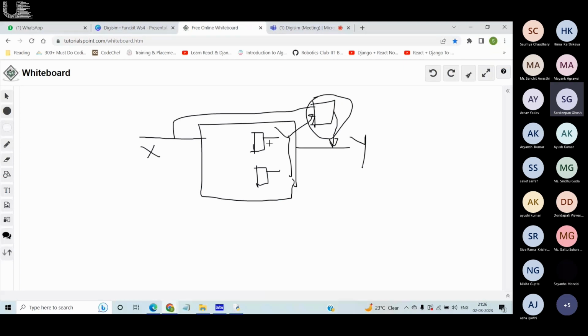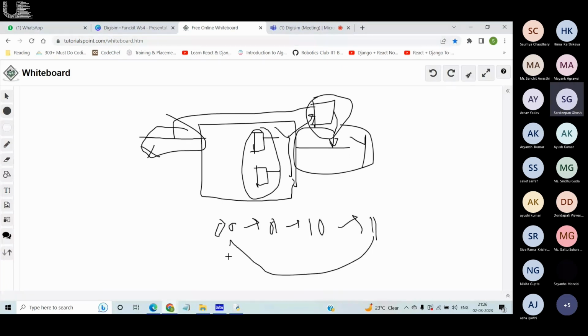And one more thing, like the one which I showed you, it may so happen that neither is there an input nor an output. It may happen that this is pre-programmed to go through a fixed number of states. Like say maybe the initial state is 00, then there is 01, then 10, then 11, and then maybe it comes back to 00. So in this device, there is no input, nor an output. The output is simply the state. So this also may be a case, and this thing is exactly what we call a counter. It counts from 0 up till 3 and then back to 0. So I'll be covering that now.